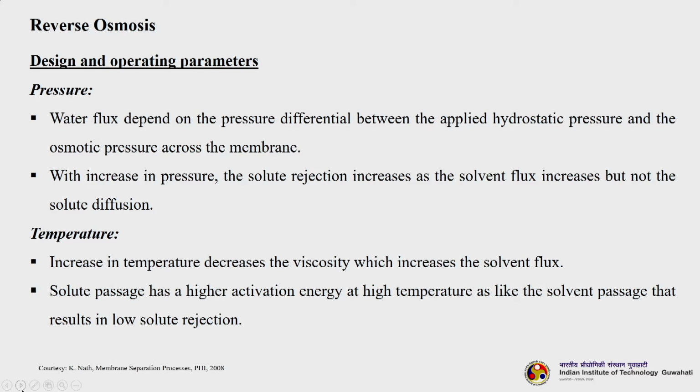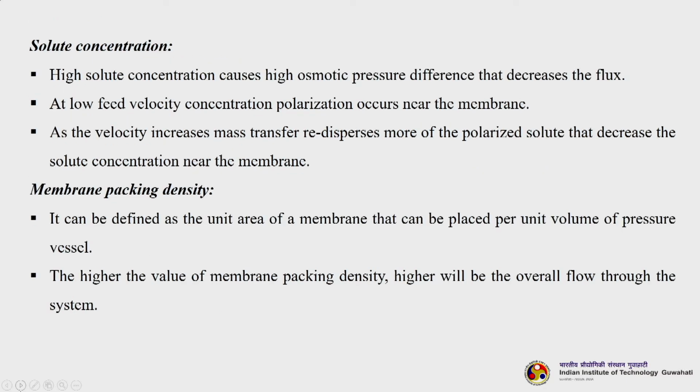Next is temperature. Increase in temperature decreases the viscosity, which eventually increases the solvent flux. Solute passage has a higher activation energy at high temperature, like the solvent passage, that results in low solute rejection. Apart from pressure and temperature, other parameters which affect the performance of RO include solute concentration. High solute concentration causes high osmotic pressure difference that decreases the flux.